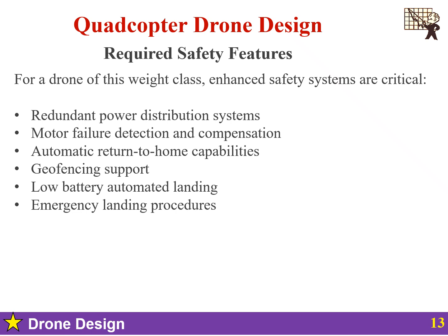For critical failures, controlled descent maintaining attitude control, a reduced descent rate for minimal impact, autorotation attempts for propulsion failure, emergency position logging for recovery.